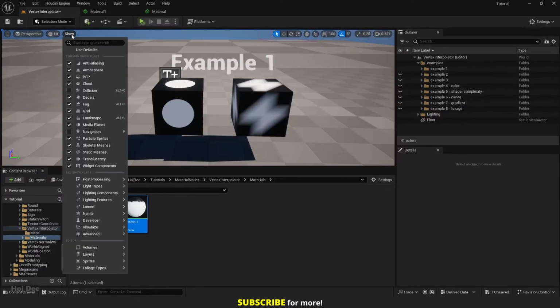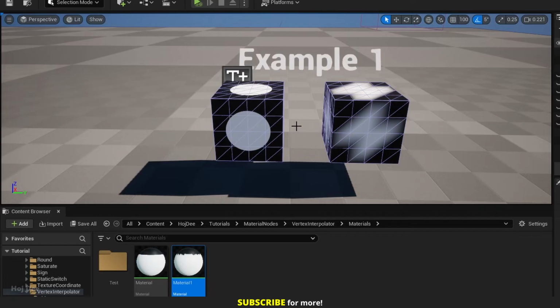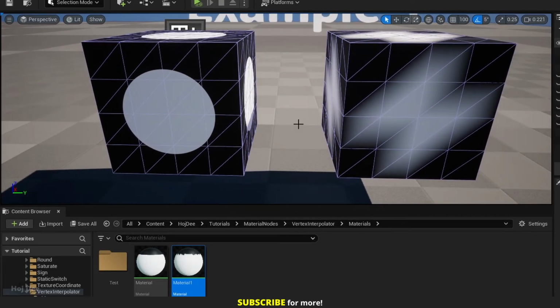Up here, click on Show and enable collision. We could also use its shortcut Alt-C. It helps us to see the edges and therefore know where the vertices are placed. We can see that when using the Vertex Interpolator node, it calculates the value at each vertex and interpolates between those values, which creates a gradient. For example, here this vertex is black and these three vertices are white.